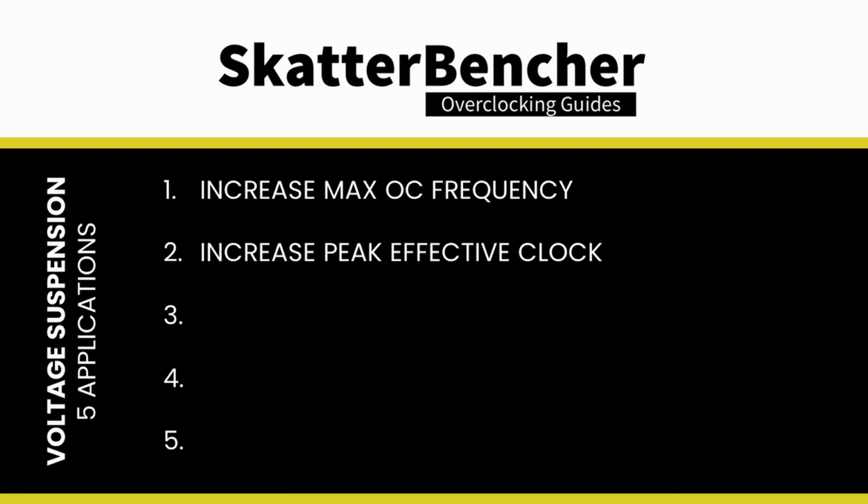Capping the peak voltage with our manual ceiling may trigger the CPU to sense the voltage for a given frequency is too low and increase the requested VID. That could help push the frequency slightly higher. Of course, you must check carefully for clock stretching, as trimming the voltage may cause instability.